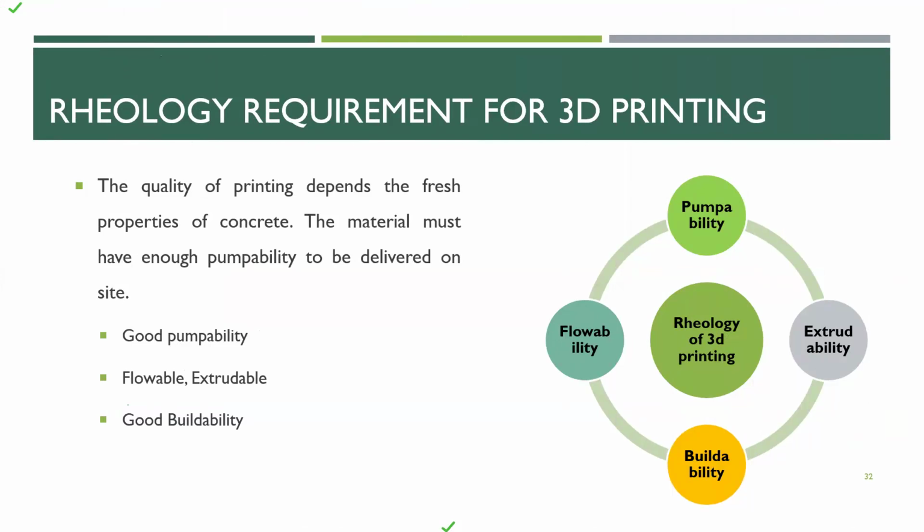It is not like workability and traditional properties. We all know that we generally do the setting time and the workability slump test for concrete, and we use these fresh properties for cast concrete. But for 3D concrete printing, these fresh properties are not enough, because if we only do the setting time and the slump flow test, it will not tell us whether the material we are preparing is printable or not. Although there is a range for flow, generally the slump flow varies around 15 to maybe 16 or 17.